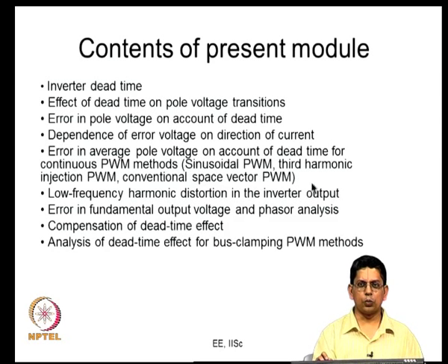So, once we are in a situation to do that, because of the dead time there is a certain inverter output. That inverter output is different from the ideal inverter output. In what sense? Actually it would have introduced certain low frequency harmonic distortion in the inverter output. This is unexpected otherwise in an inverter.